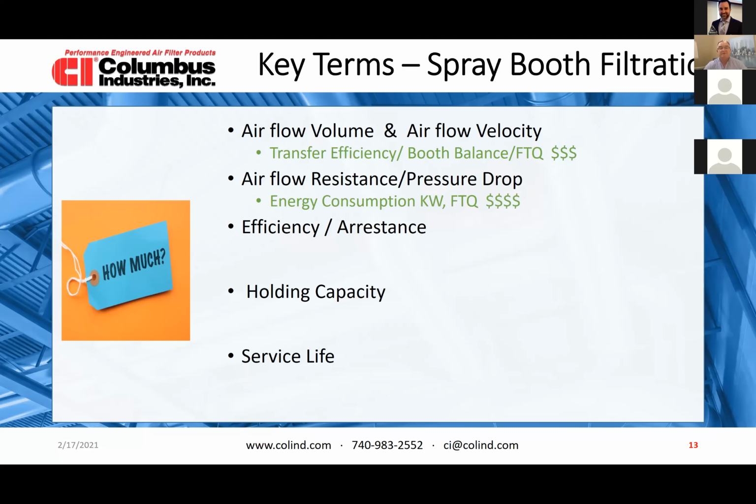Airflow resistance and pressure drop. Again, the energy consumption, the first time quality also means dollars. To move a certain number of cubic feet per minute through a filter that's high resistance, you're going to spend a lot of energy. And in today's industry, a lot of the booths do have a drive that controls the speed of the fan to make sure the airflow is constant within the booth. So if the filter is higher resistance, it's going to work harder to pull that amount of air through. So it's going to cost money.